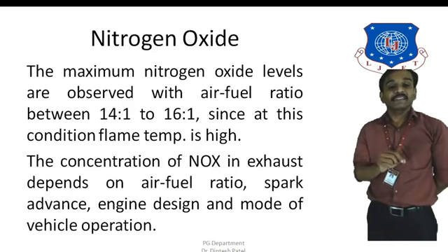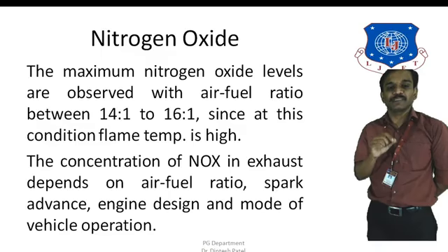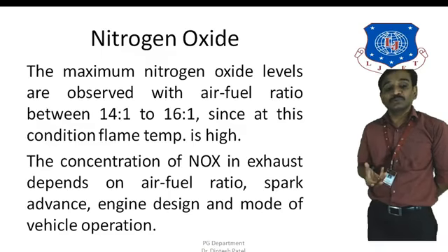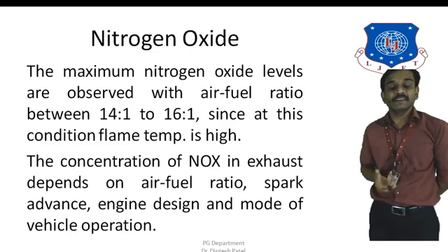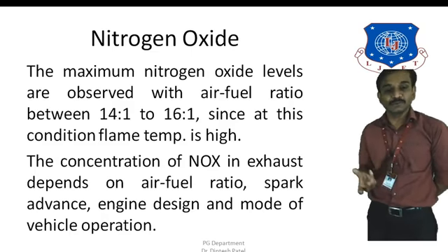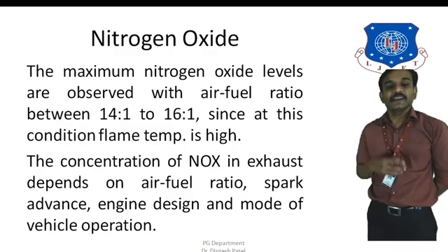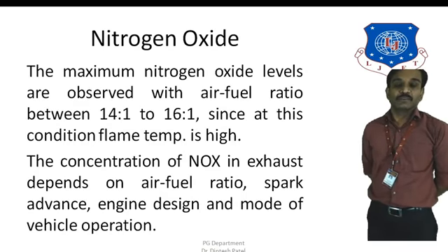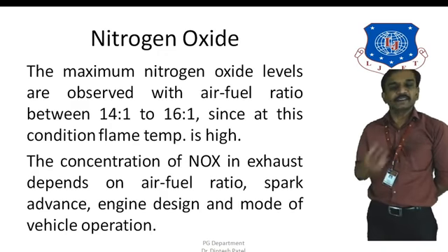Because at that time the flame temperature is highest, and nitrogen oxide is always highest when there is the highest temperature, right? The concentration of nitrogen oxide is not only dependent on temperature, but it also depends on the air-fuel ratio, spark advance, engine design, and mode of vehicle propulsion. Pressure also plays an important role, because pressure is directly proportional to temperature.